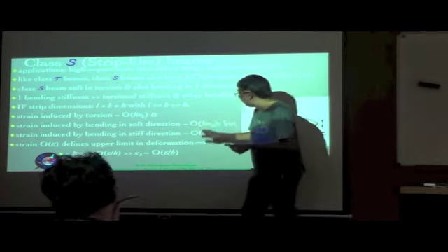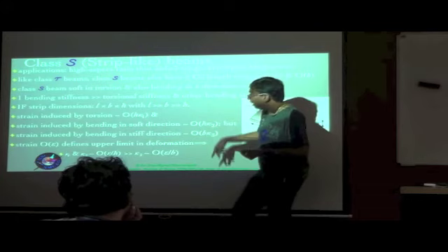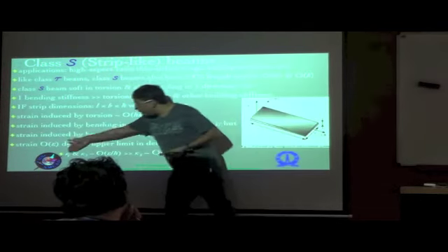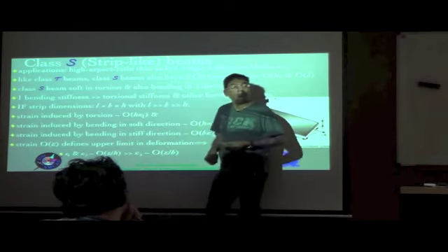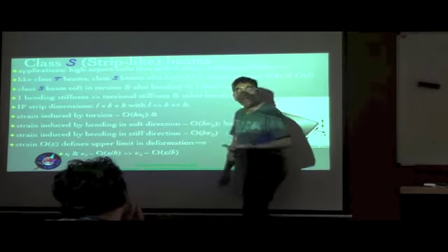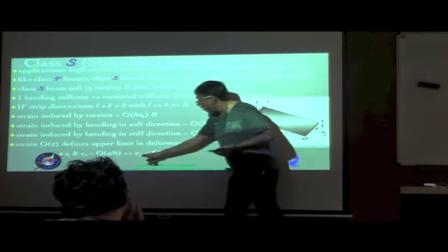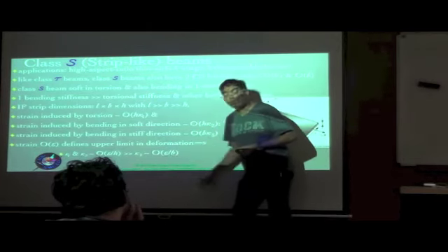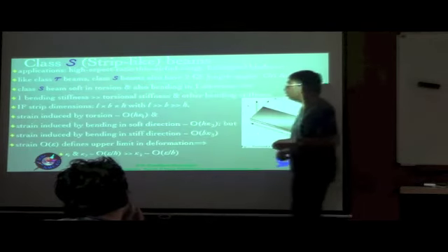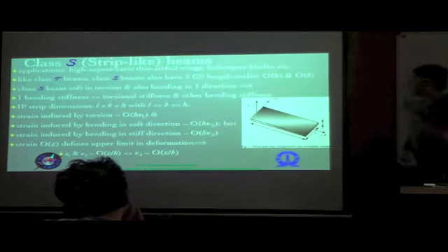So once we compare each one of these 3 with epsilon, it's very clear that kappa 1 and kappa 2, that is basically the twist per unit length and the curvature about the softer direction, are of the order of epsilon by h, whereas about the stiffer direction the bending curvature is going to be epsilon by b. Once again, the fact that h is very small compared to b basically means that kappa 1 and kappa 2 are much larger compared to kappa 3.